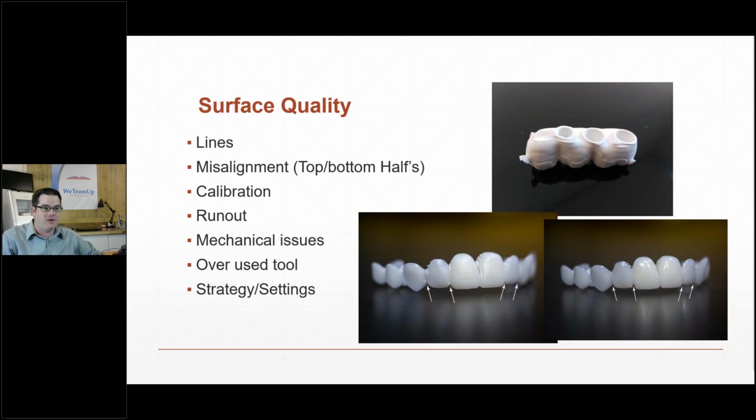What that is, is when the puck gets flipped, it's not aligned perfectly in either an X or Y direction, and so you get an offset. If you ever have a machine that's doing that, pay attention to the direction of the offset, which axis it'll be aligned to. If you can tell your support team that, it'll help them zero in on what to make an adjustment on.